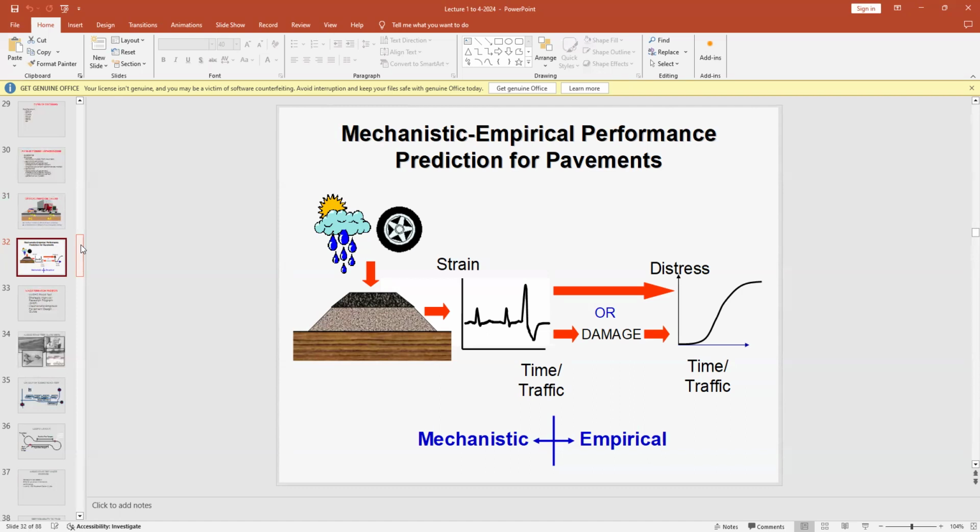So that's why you have the subgrade, but then you have to do other measures to make this subgrade resilient so that it can accommodate water, one by allowing it, or if it is not, then you provide some drains underneath as well that can collect the water. So it's a science.